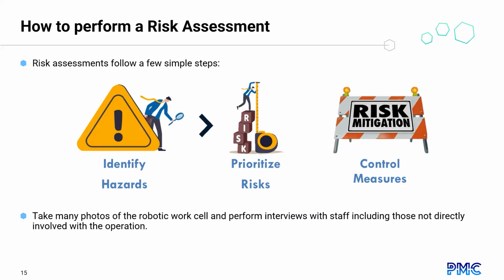Conducting an interview with the operator and people who know the process helps to carry out the risk assessment. In addition, recording videos and taking pictures of the operators' workstations, the obstacles around the operator, all the areas, infrastructure, the robots working around the operator, and the machines and the production. All of these help us to analyze and identify hazards in our facility.